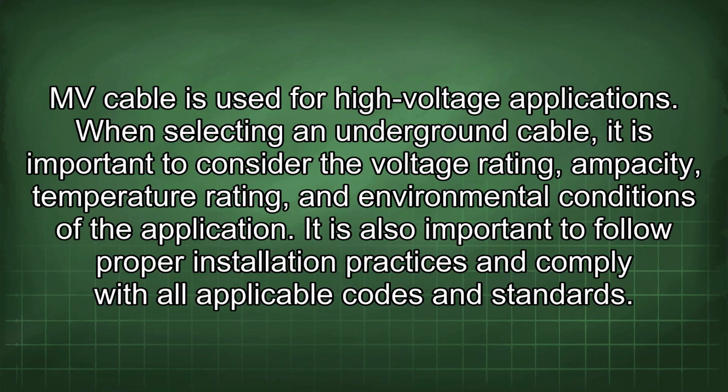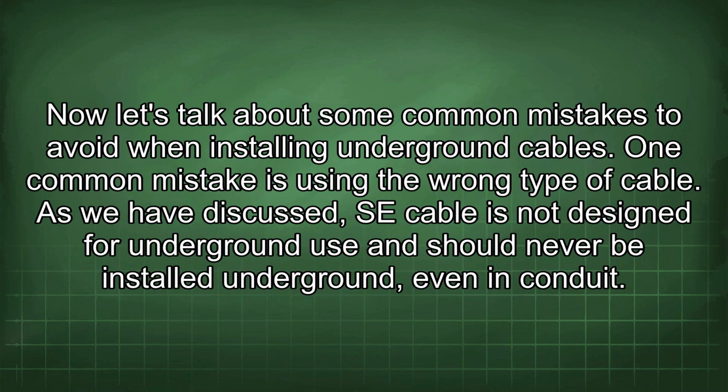When selecting an underground cable, it is important to consider the voltage rating, ampacity, temperature rating, and environmental conditions of the application. It is also important to follow proper installation practices and comply with all applicable codes and standards. Now let's talk about some common mistakes to avoid when installing underground cables.